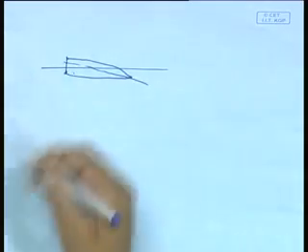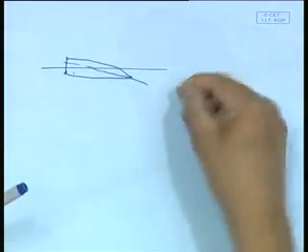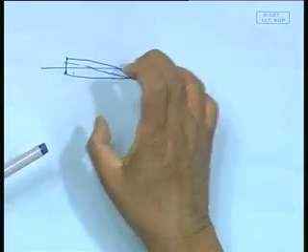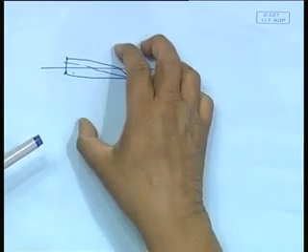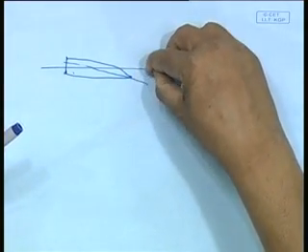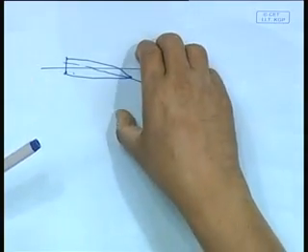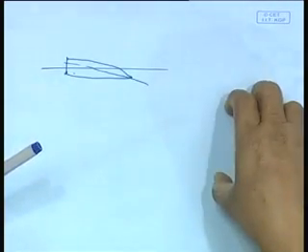There is no rudder, I somehow pushed it. Immediately forces got created on it, because the flow is no longer a straight line. Now what I want to know is whether the force and moment created are such that they will tend to make this angle theta zero, meaning the ship will try to align itself in the direction of motion.